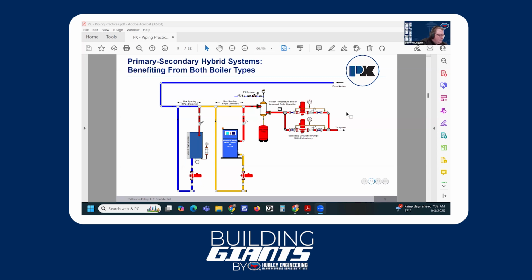Two, we've got to have the control, the temperature that we're measuring, downstream of both boilers. Now that's true for most heating applications, but it still holds true for hybrid applications. Our control is still going to be, if you'll follow my cursor, this point downstream of both of them. And we have to monitor that mixed or common temperature. Then ideally, our control would also prioritize our condensing boiler. That's to gain the efficiency, to have the benefit of this condensing boiler, we want to prioritize it at all times.